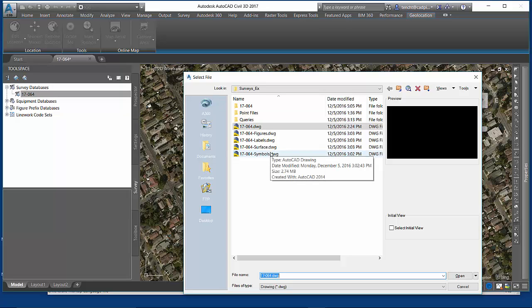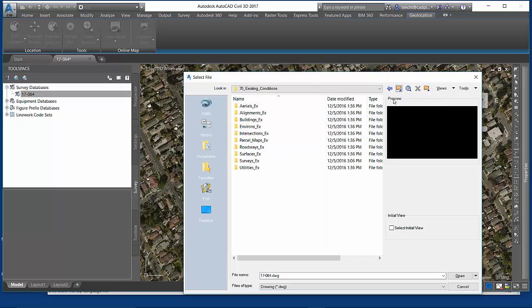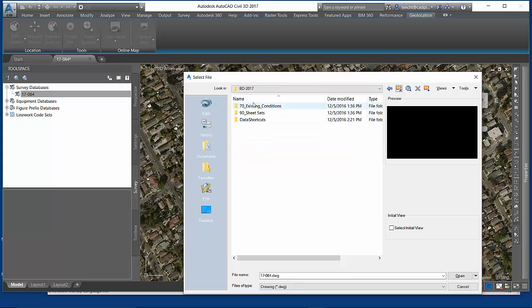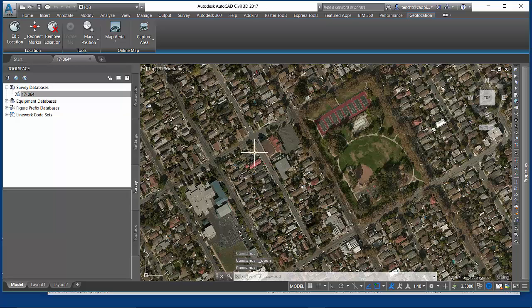This is a very typical survey project. Already made a series of standardized drawings. Got a container for my survey database. I've imported my typical queries that I use to process files all the time. And uphill, I've got folders to hold my output and other stuff I might get regarding this project all built. Here's my project. It was really made from a Civil 3D template. In other words, just a folder structure with the standard drawings and all the stuff that I typically want to have available to me when I start a project.